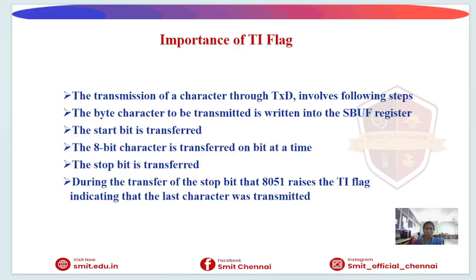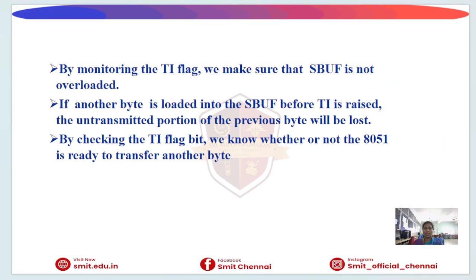Once the stop bit transmission begins, the 8051 automatically sets the TI flag to 1. This indicates that the entire character has been transmitted successfully. The TI flag helps the programmer know when the microcontroller is ready to send the next character. This is the importance of the TI flag. Why is the TI flag important?